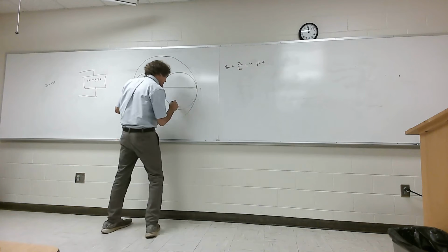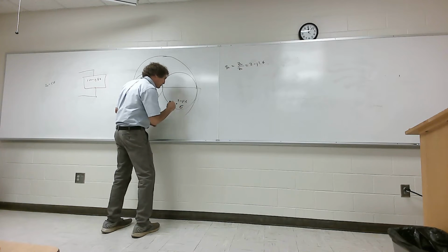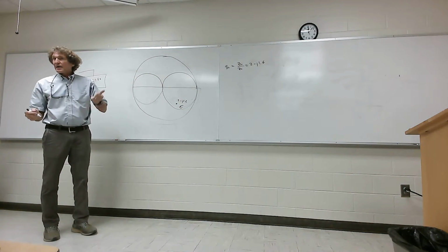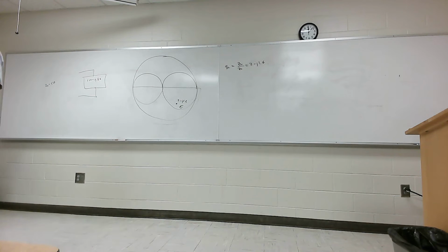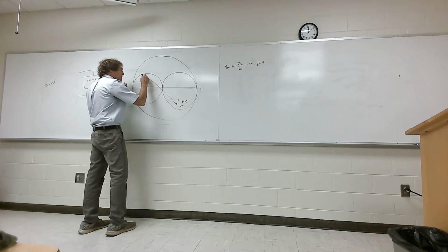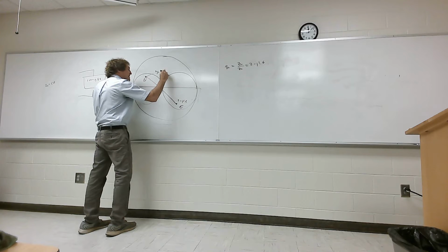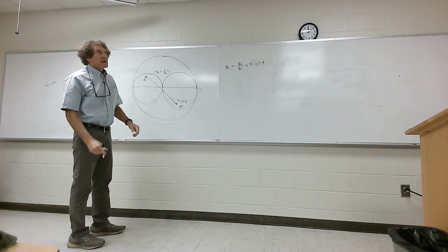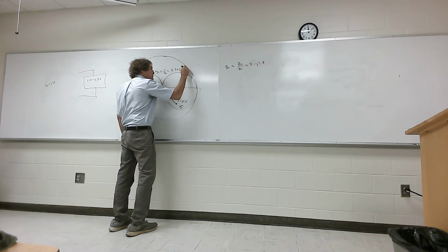We plot that point somewhere around here. And that's my first point, right? Then I go to the opposite. I can't get to the one circle no matter what value of J I add here. So I have to go to the admittance domain. Now that's point 1. Now I come through here and I go to the admittance domain. That's my second point, and that's just YL is 1 over ZL. And that was 0.39 plus J 0.24, I think.